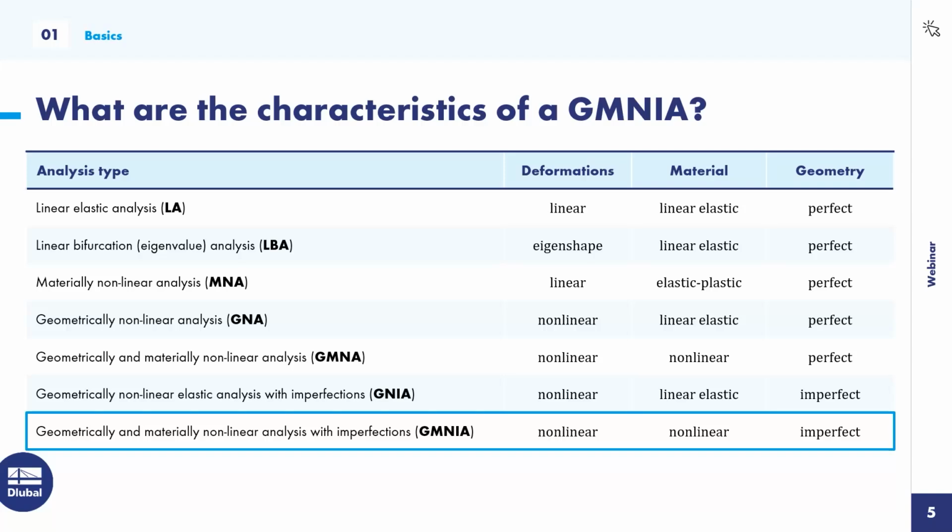To be honest, we could also design a standard plate girder that we tackle in our example today using formulas given in Eurocode 3 Part 1.1 and Part 1.5. However, if we want to examine special design variants of such standard girder, e.g. the influence of web openings in critical regions, or we want to investigate how the plate girder performs when we use corrugated webs instead of plain ones, or we have discontinuous sections. In these cases, a GMNEA can often be the most economical design method.